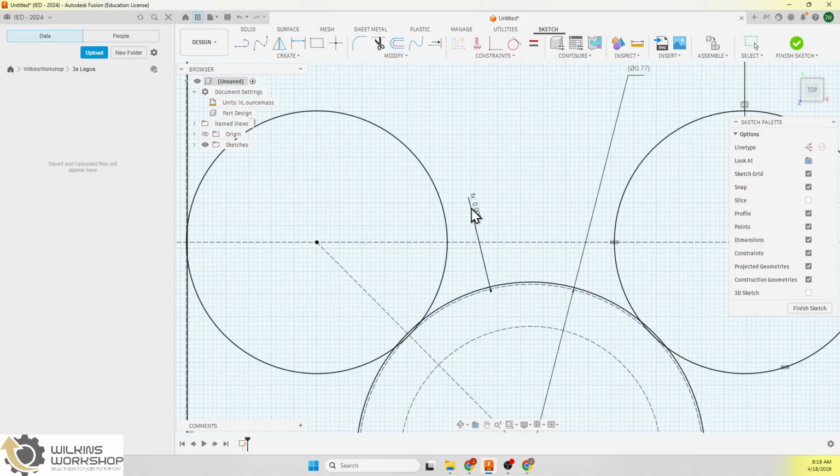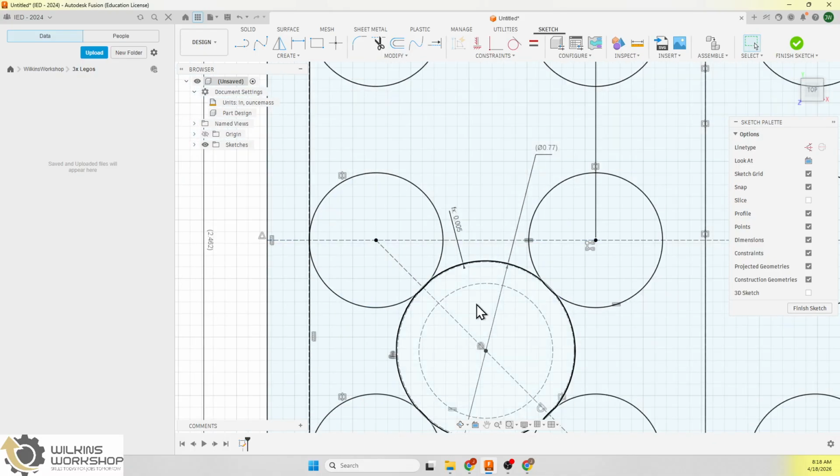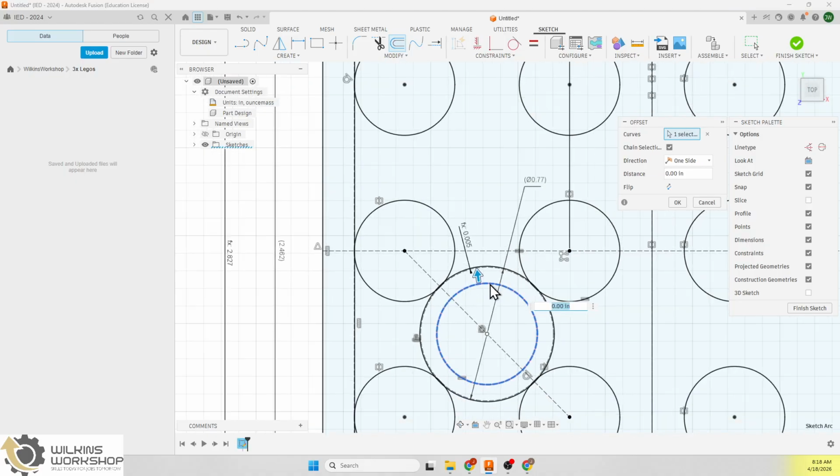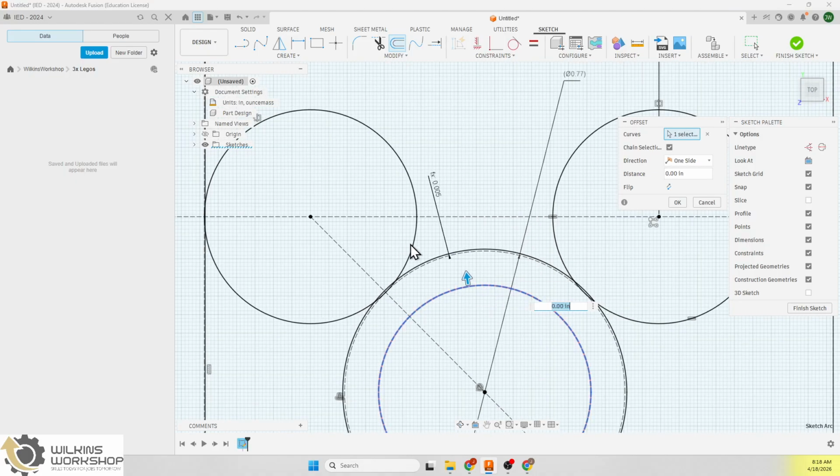So I'm just going to pull this out, so if we ever need to reference it, it's right there. And then this one, we're doing an offset so that the stud can fit in there. If we make it the same size as the top of the stud, it's not going to fit. It won't press fit into there. Or if you press fit it in, it isn't coming out because it's too tight. So this one we're going to make kerf a little bit bigger, and you're like, well, why is it not kerf times 5/4? Well, again, this is just through testing. We want it to insert into there. We want it to stay. We don't want it to be sloppy in there, but we also want it to come out. So we're making it basically a little bit bigger.